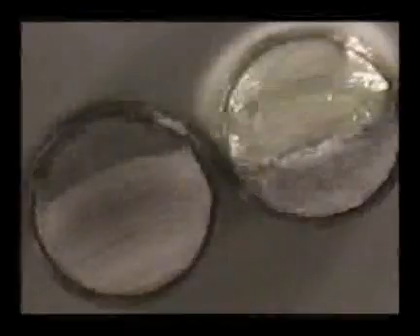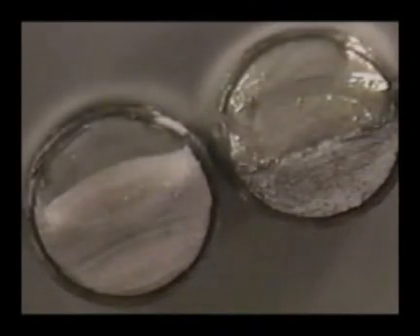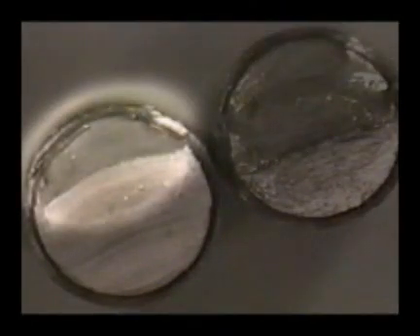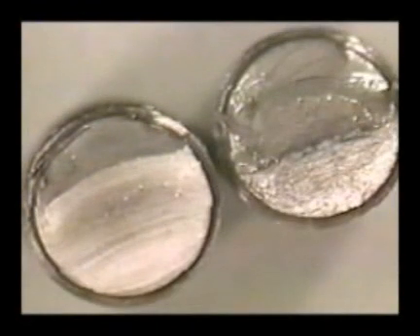The bolt on the right has a much larger final fracture than the bolt on the left, suggesting it experienced excessive cyclic loading. The fatigue crack didn't have to progress nearly as far before the remaining metal was overloaded and failed.